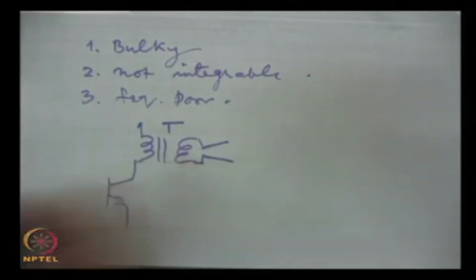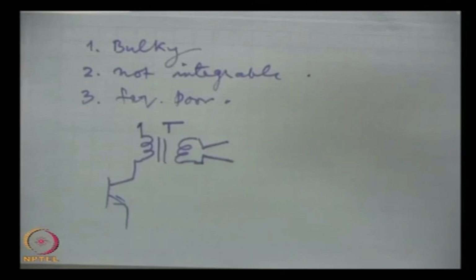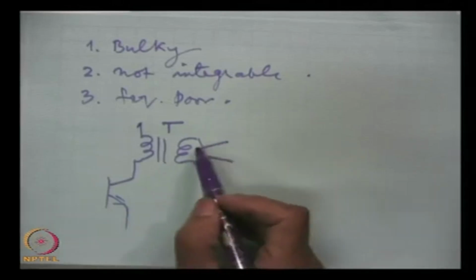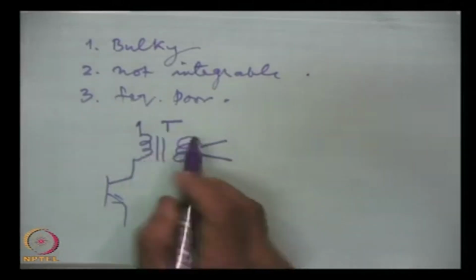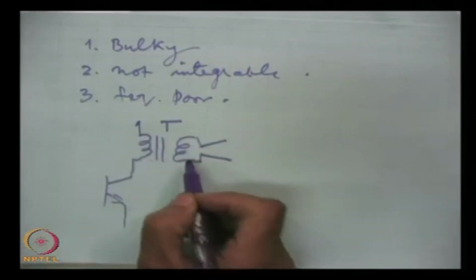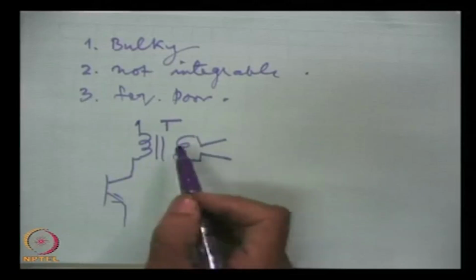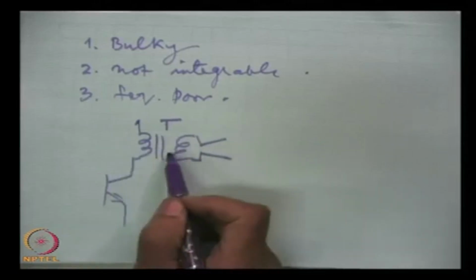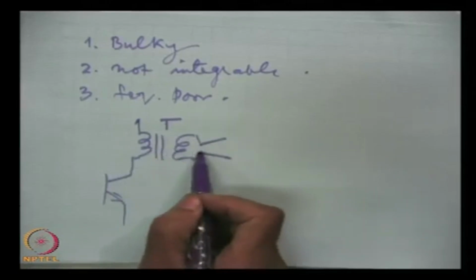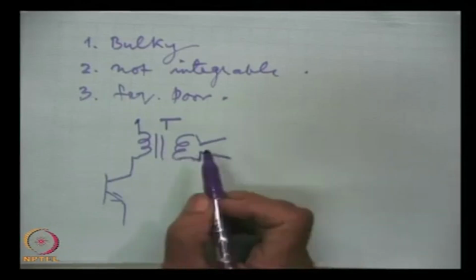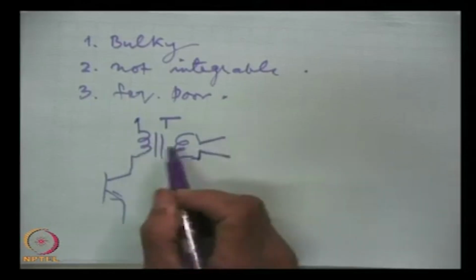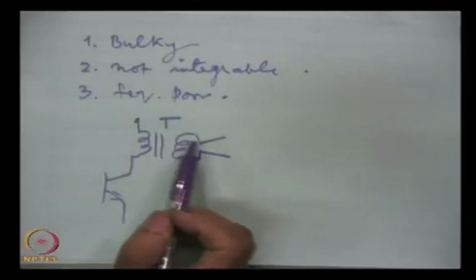If you open your radio sets, transistor sets, you may find the speaker connected to a transformer. In this transformer coupling, large currents can be taken and hence large signals can be passed through the transformer, and DC will be blocked, no DC will propagate in the transformer.